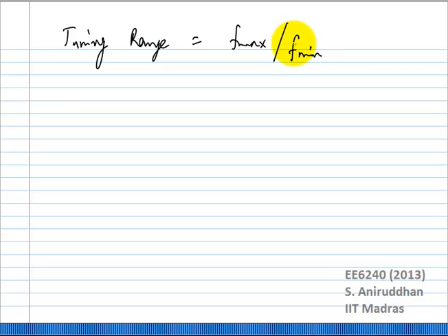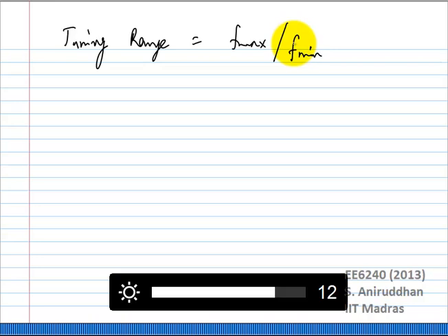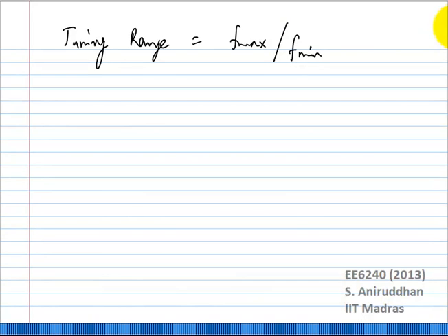Maybe I have a band from, let us say, I'll just give you approximate frequencies, maybe 800 to 850 megahertz. I have another band from 900 to 950 megahertz. Maybe I have other bands also, but I have one band from 1800 to 1850, and I have another band from 1900 to 1950. Okay? I have these 4 bands. Are you going to have 4 PLLs?